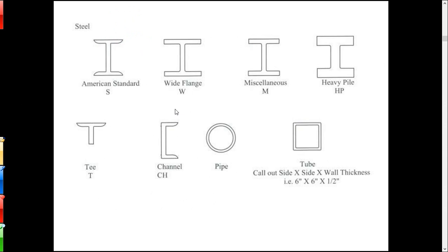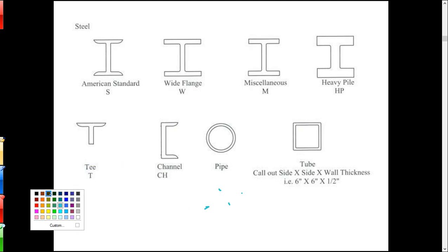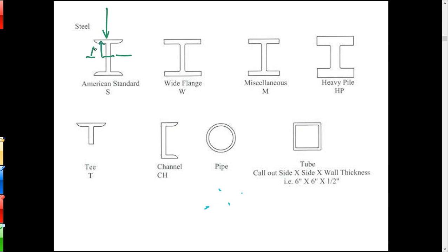So back around the turn of the century, a little later into the century, like when they were building the Empire State Building, they used standard shape beams, okay? Those were the standard of the day, and that's obviously why they're called standards, okay? So what the deal is there is, if you load these up, they're very strong in the Y direction, because what you've done there is put most of the material out away from the neutral axis. You've maximized that Y part of the equation.